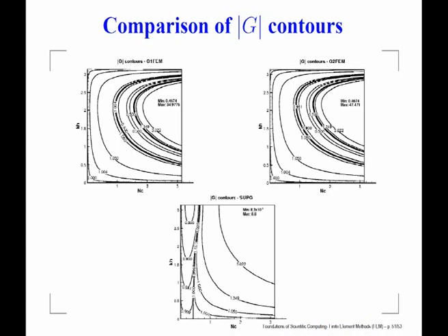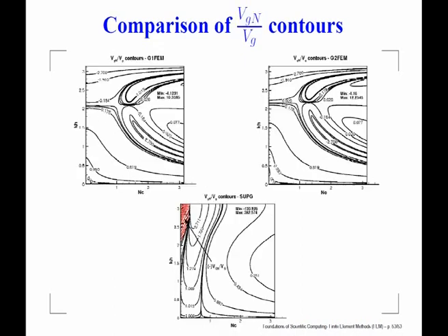So, this is a 0.5 line, right. So, you will not get upstream propagating waves in actual computation ever, but there is this possibility that if you excite the flow forcibly in that region with a large amplitude disturbance, then you may actually get this spurious propagation. Okay, I think this is all that I wanted to tell you about this.